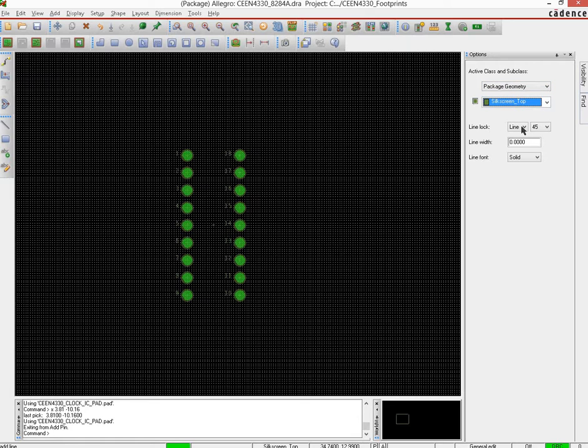The lines are fine, but the line width needs to be at least some non-zero value. I'm choosing 1. And then I'd create a box around this so that I know that it's a rectangular component, and I'll edit the box in a way so that the pin 1 location is indicated a little bit differently. So again, I'll use the X command to do that.